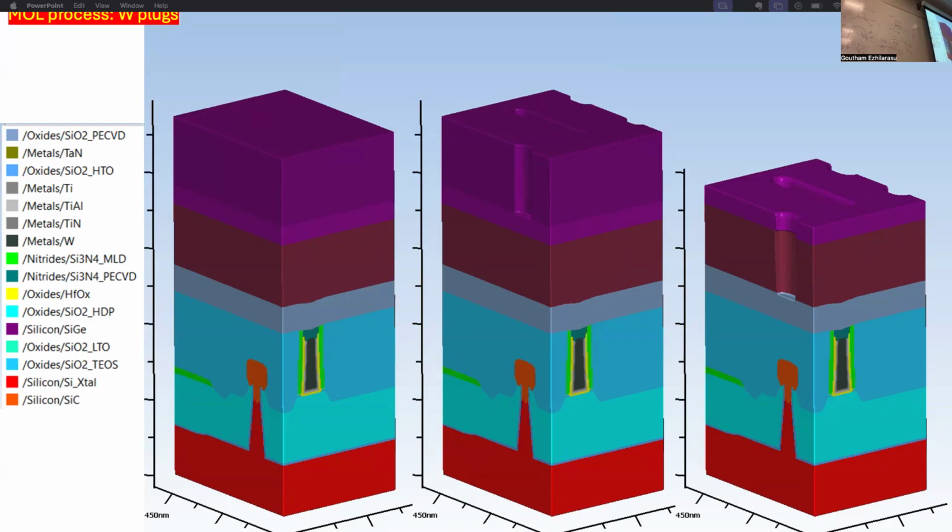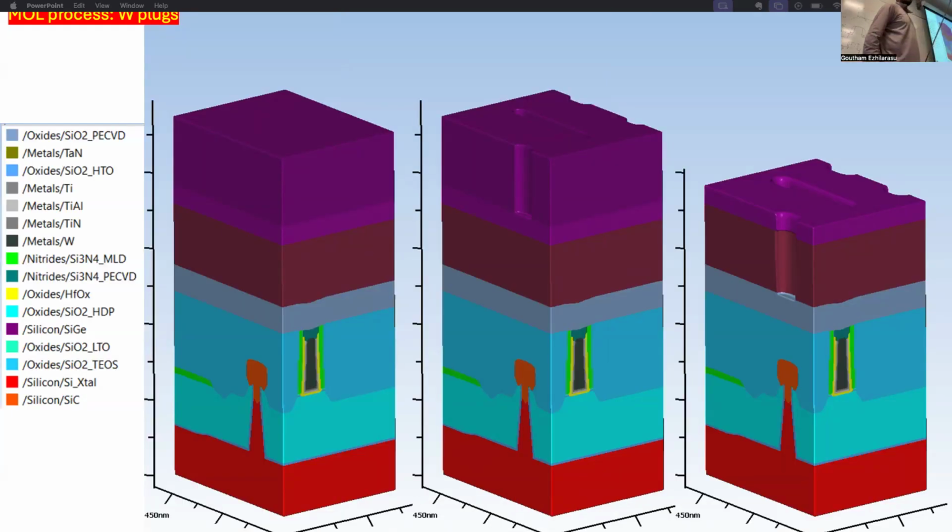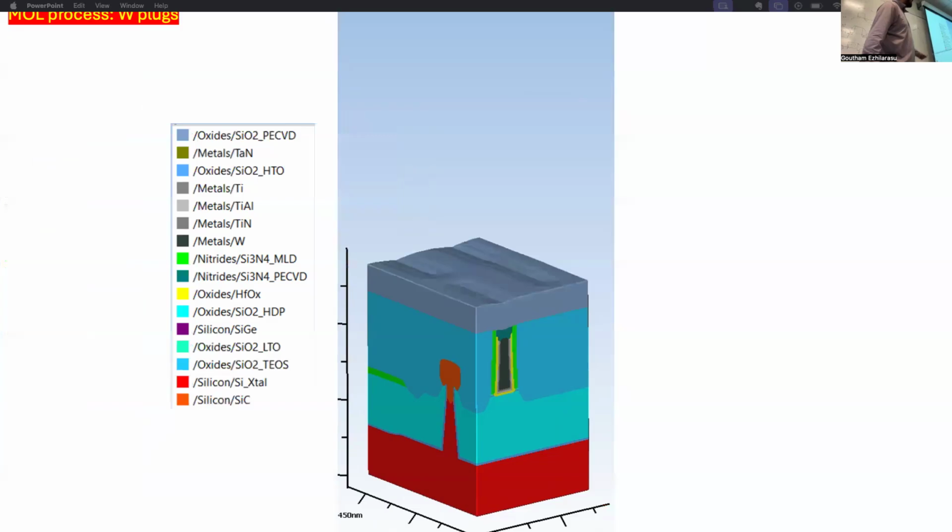So what is that darker layer here that we put after the nitride cap? This is just some oxide. Yeah. It's just some oxide that I planarized with CMP. It's the material that's on the tungsten? That's nitride. It's a nitride capping layer, actually.